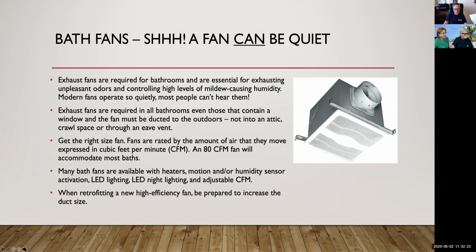Frameless cabinets, or the European style, which is shown with the tilt-up door in the bottom photo, are sleeker designs, but they don't have to be modern. They can be anything, really. The style is set by the doors and the drawers. These are more vulnerable to what's called racking, which causes the cabinets to become out of square. IKEA cabinets are an example of Euro-style cabinets. And some warnings for you: some cabinet manufacturers do charge much more for the Euro-style cabinets than the face frame cabinets because of demand.